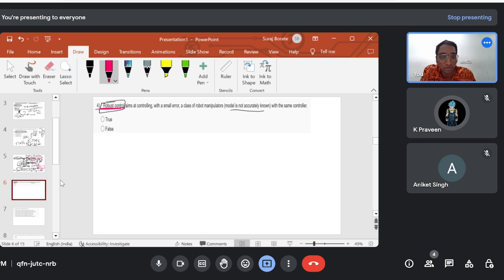So for example, let's say this is the path that the robot has to follow, and the robot is, let's say, here. So let's say this is the error, x error. Let's focus on only one error. So what does Kp into e mean? Desired was 0, your robot is, let's say, at -1.